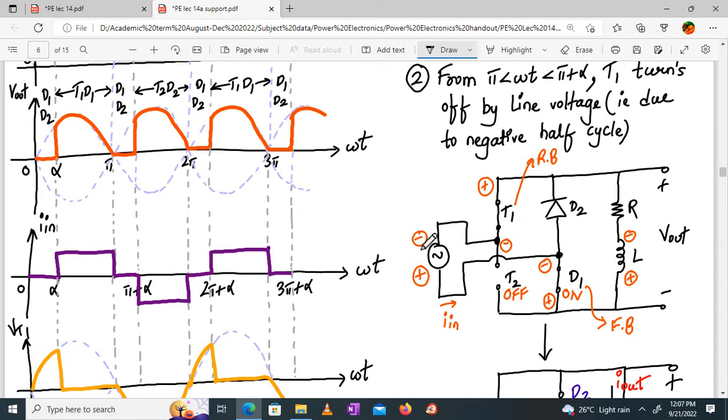अभी क्या हो रहा है, ये वर्डिंग्स देखो. अभी नेगेटिव हाफ साइकिल में गए, so this negative will come over here. This positive will come over here. This positive will come over here. Right? Correct? And inductor stored energy is releasing now. So, abhi inductor stored energy is releasing its polarities like this. Right? So what this is doing, now due to this arrangement, what is happening?